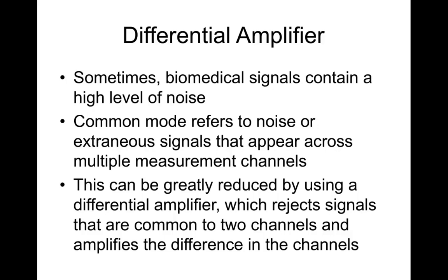So what the differential measurement does is it takes signal number 1 and it subtracts signal number 2, and there's an assumption that if the probes are similarly designed and the source of unwanted noise is well defined and characterized, then taking the difference will eliminate the noise.